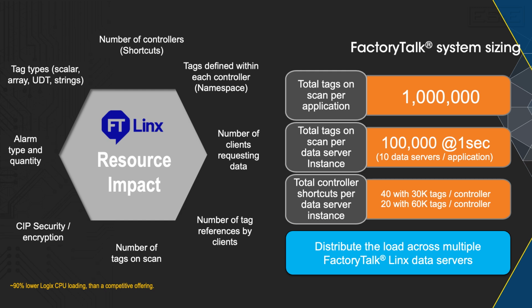If you've ever set up FactoryTalk ME, right? Those of you who use Ignition, if you ever set up PanelView Pluses and things like that, you're going through and you're creating these shortcuts. You're defining data servers. That's what you're doing. Those are data servers, all right? It's just when you get to SE, you can start having more than one data server inside an SE application. Truth of the matter is, an application is not necessarily an SE application. It is a FactoryTalk application, okay? So if I just had FactoryTalk Link Gateway, I went into FactoryTalk Administration Console, and I'd create an application, and then in that application I start adding data servers. That's what you're doing. You're doing this right here.